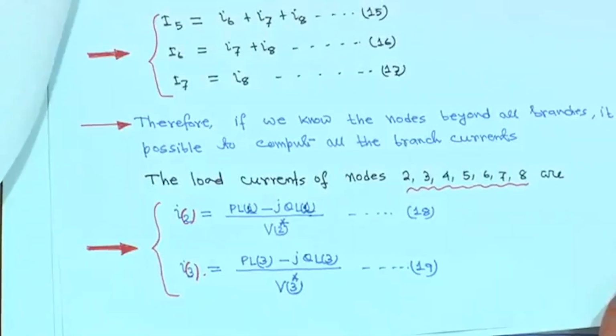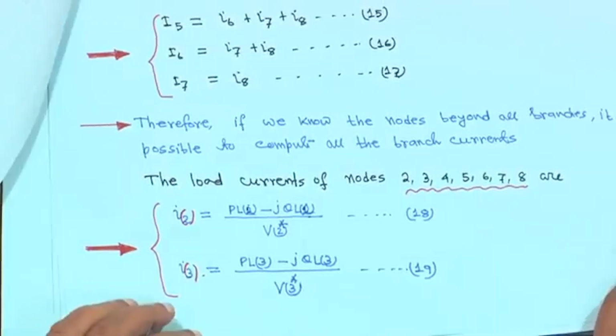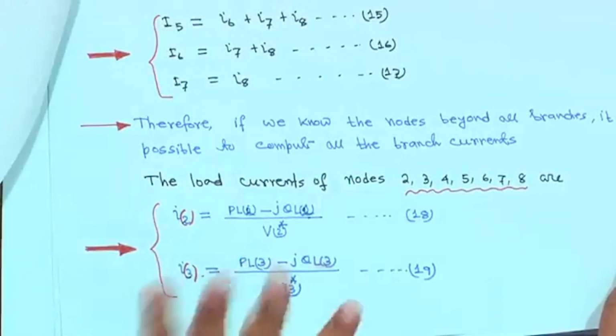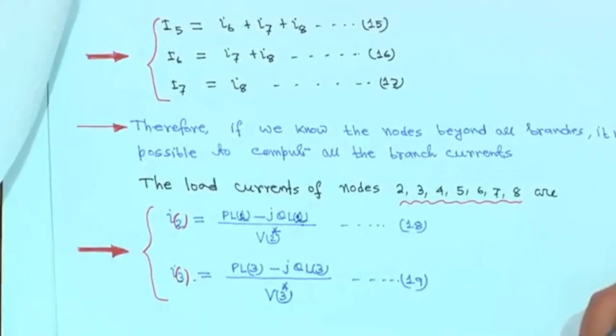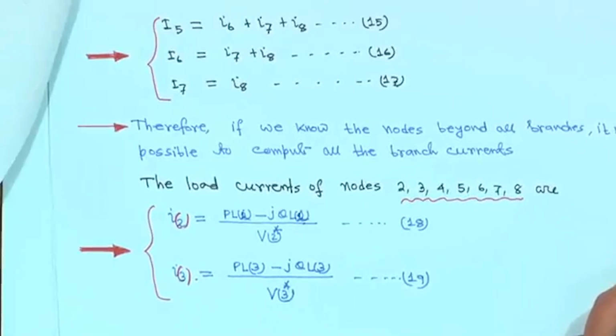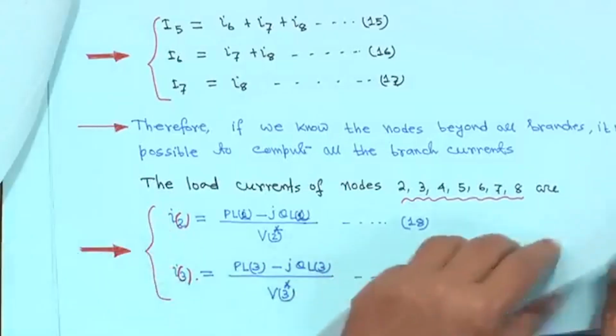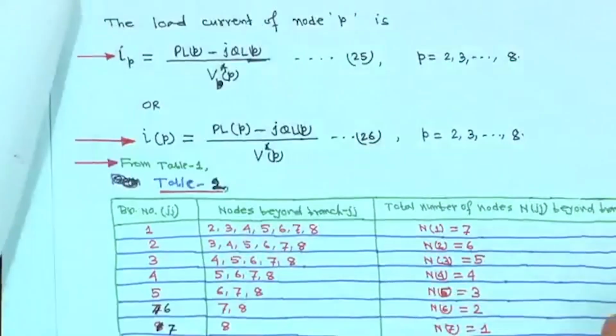So, in load flow studies you know that we start with a flat voltage. For V2, V3, V4, all these initial values will be considered as the slack bus voltage, such that the initial values of I2, I3 all can be computed. We will come to that, right.